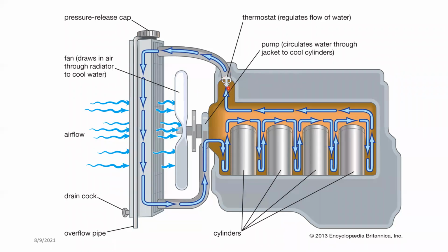Once this valve is open, the coolant will then be sent back to the coolant heat exchanger or radiator, then passes down again through very small thin channels where air is in contact with the body of these channels, where it actually takes away the heat.